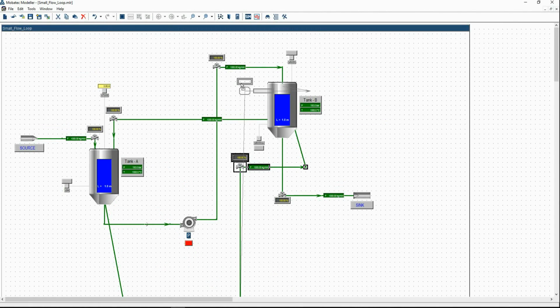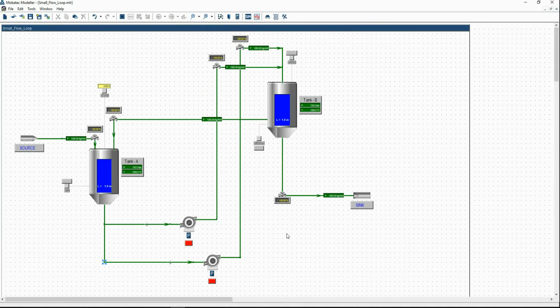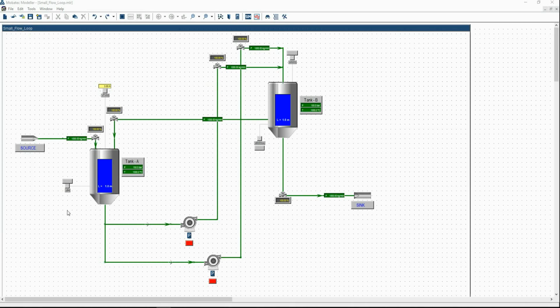Let's adjust the upper line first, the way we want, and let's adjust pump position the way we want as well, using the same techniques as shown in previous steps. So now we have a spare pump. Now we have to change the name of the second pump, as we cannot have two model objects with the same given name. So do a right click on the second pump, go rename, or use F2 on your keyboard. Change its name to spare, rename. Okay, there we have it.